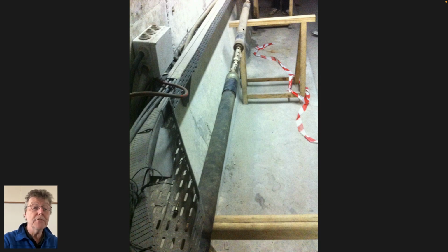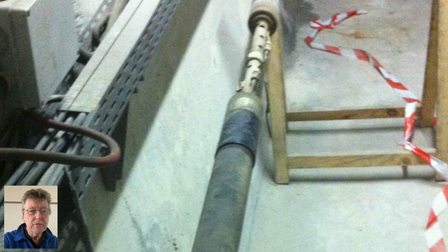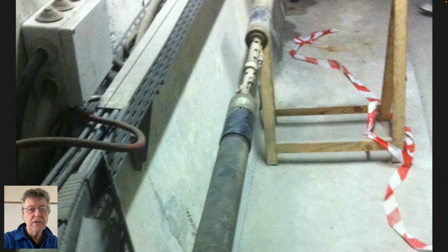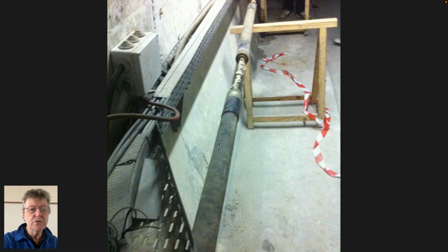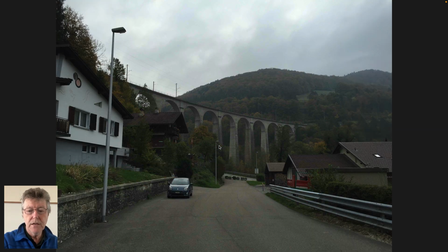So this is a different place. This is in a French former nuclear ballistic launch underground site where they had ballistic missiles, now decommissioned for running experiments. And this is a straddle packer. The upper packer, the lower packer, the straddle zone where you measure fluid pressures or inject fluids, the small line that links the upper packer to the lower packer for the air tank, and then this whole assembly is introduced in the borehole and then isolates the upper and lower zone where you can do these experiments. Yeah, the doors, heavy doors within this. Again, Switzerland.